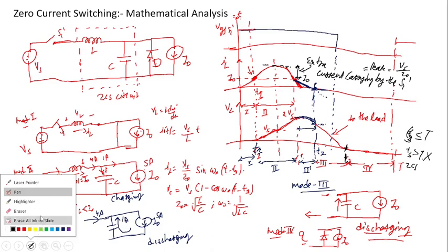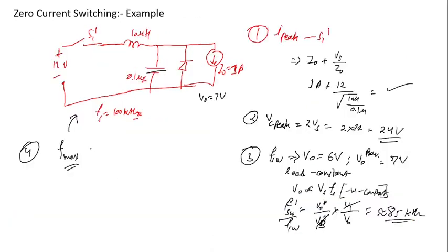Why? You have to check it. So the maximum frequency will be achieved by this time period, this time T3. Always remember, T3 depends on the L and C. So you cannot put maximum frequency. To achieve the maximum frequency, 1 upon T should be there. T is varying in nature because that is in our hand, but T3 is not in our hand. It highly depends on the L and C. That is the reason I have put T3 in the denominator.